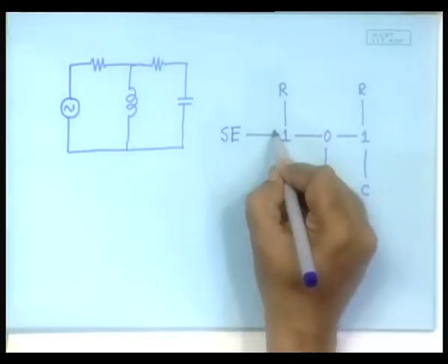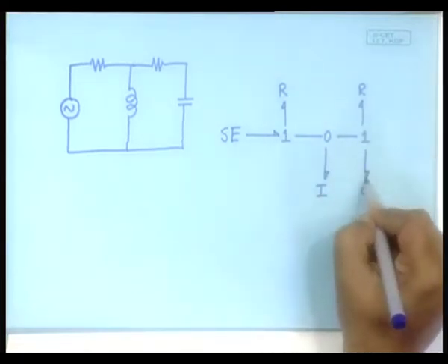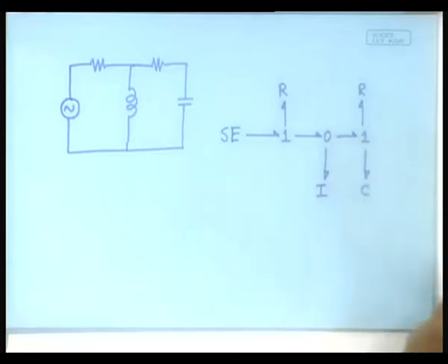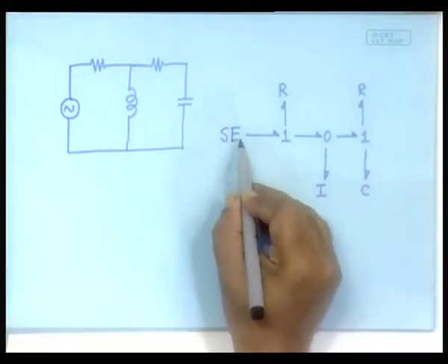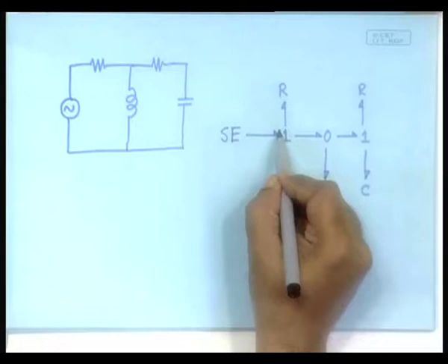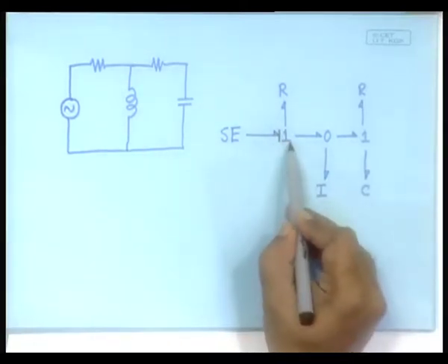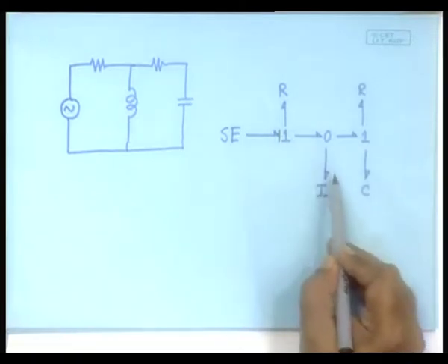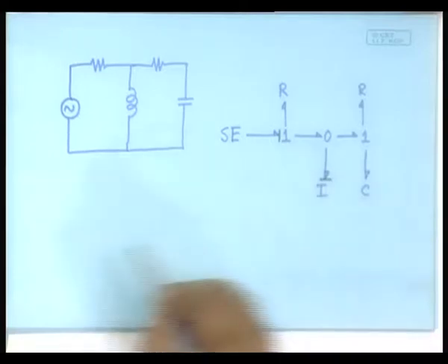So, give the power directions, which would be somewhat simple. Now, start giving the causalities. The SE element will give the effort information to the rest of the system. So, the causal stroke should be here. As yet this value is not determined. So, let us go straight to the I element. The I element's natural causality would be like this.